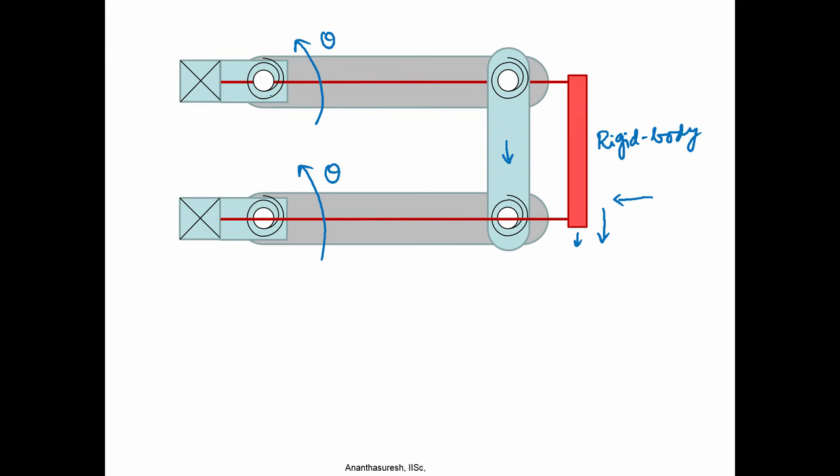So, the PRB model enables us to analyze things that are complicated. This is not that complicated, the first example. It can be complicated, and we can analyze it with a one parameter model by making a 1 degree of freedom pseudo rigid body model of the mechanism. So, here the red one is the real mechanism, the one that we have with rigid bodies, and this one is a replacement of this red thing, with 4 joints,